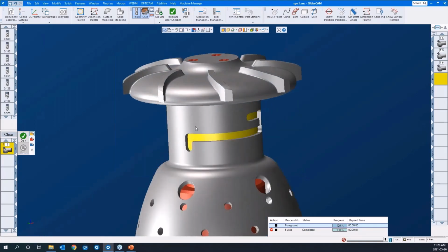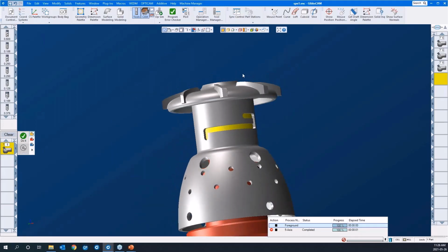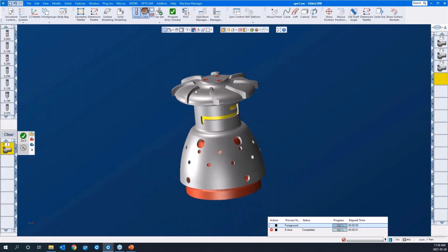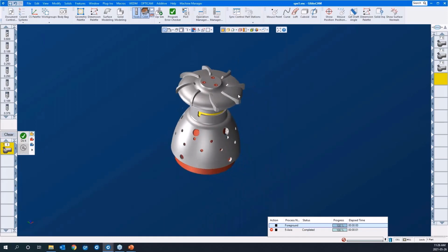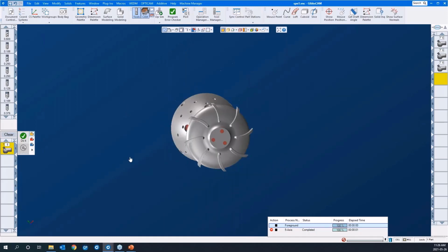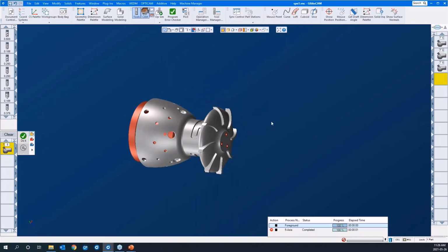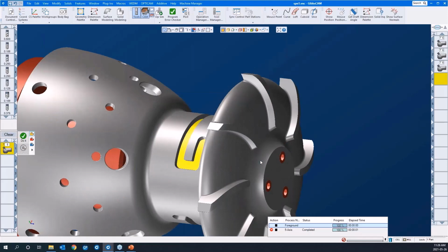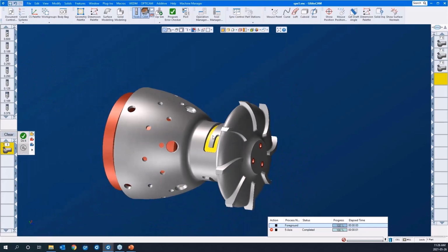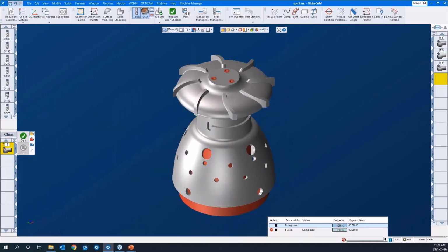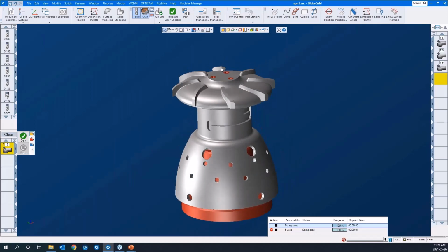Okay, we're going to look at this radial slot here. This is a 5-axis machine, has full 5-axis on it. However, if we were to rotate the part along the trunnion axis 90 degrees and access this slot, in a sense, we're now on a 4-axis mill. Although this is 5-axis, this certainly can be done on your 5-axis or your 4-axis vertical mill or horizontal for that matter.